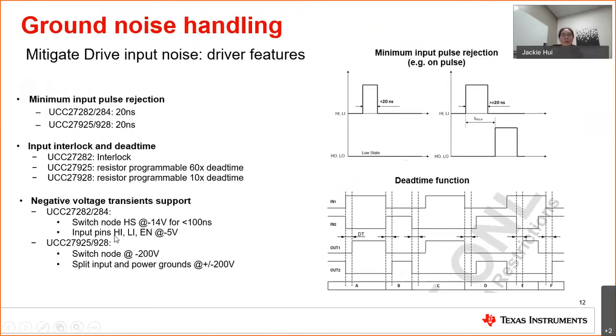But keep in mind, even though the switching noise tolerance on this driver is pretty high from a negative voltage aspect, it doesn't mean that you want to have significant switching noise, even though the driver will not be damaged at the switching node. Remember, the negative voltage can cause overvoltage on your bootstrap circuit, so you still want to limit your switching node even when using this new type of driver.